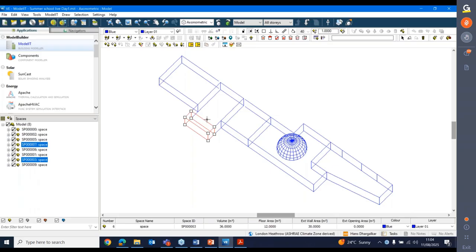Those are the modeling rules for compliance. Okay, and if you have a hole between zones, as I said, you will get daylight, airflow, sunlight transmitted through that hole. You can always delete the hole. You can always put one hole back in. You're never stuck. So you can always go and delete a hole or put one back in if you wish to. Okay, let's undo that.